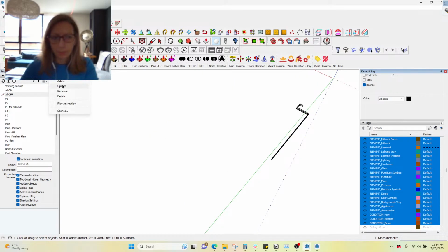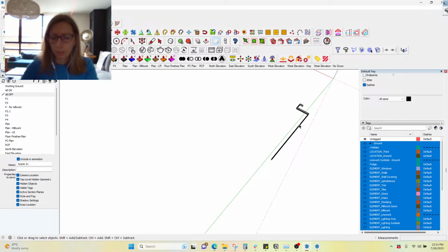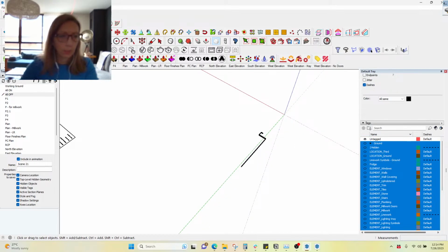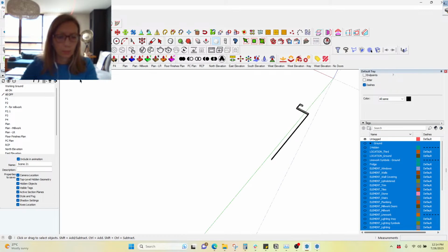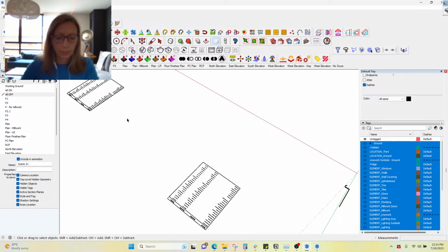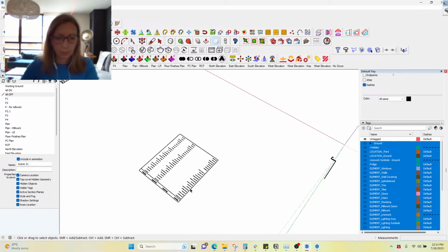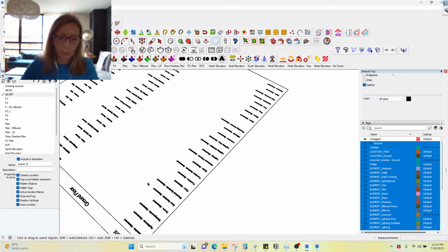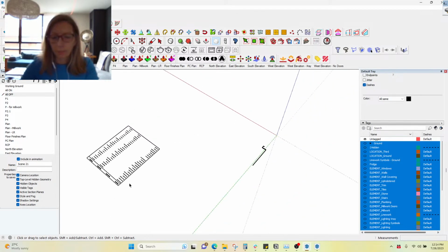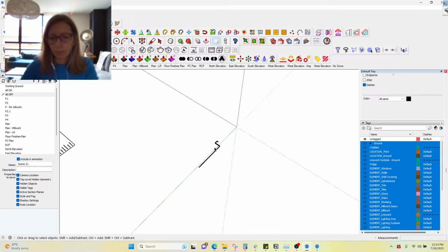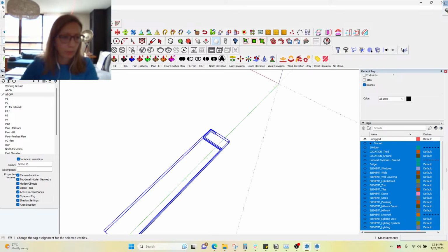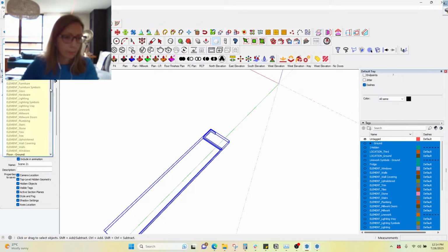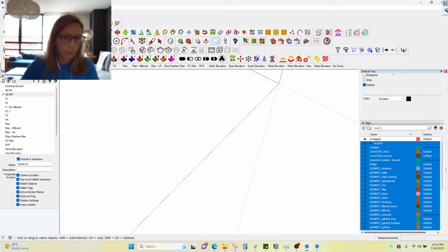And what this helps me do is see what I have that is on untagged. So the only thing that I see in all off, and I'm going to actually zoom extents so I see everything, these are sort of part of my template. It's all of my tags. So the only thing really that's on here and hasn't been put onto a tag is this baseboard trim here. So I'm going to go in and put it onto trim, and so that goes away.